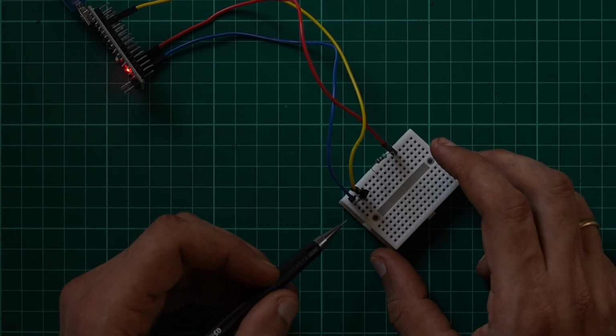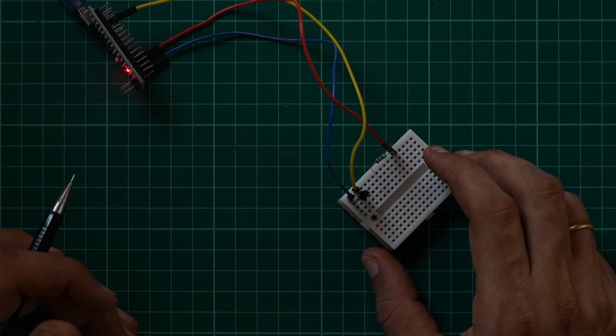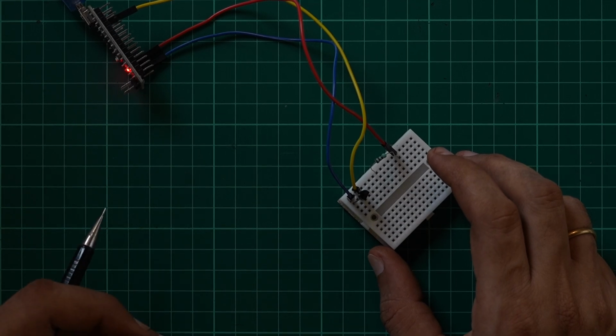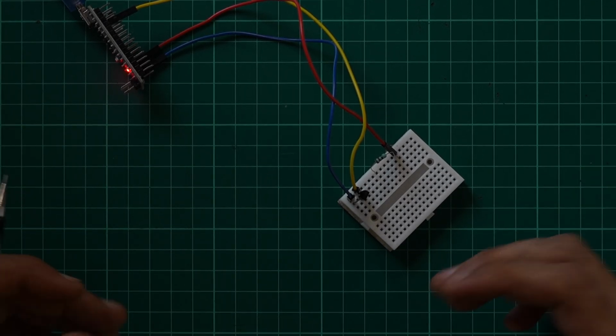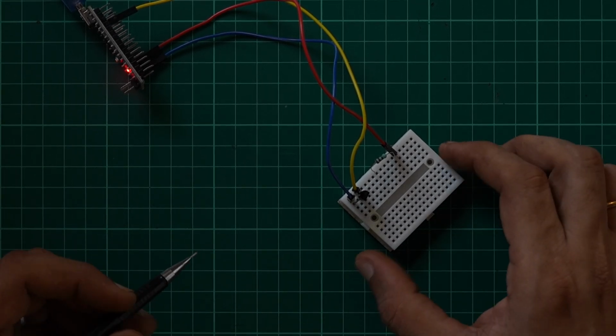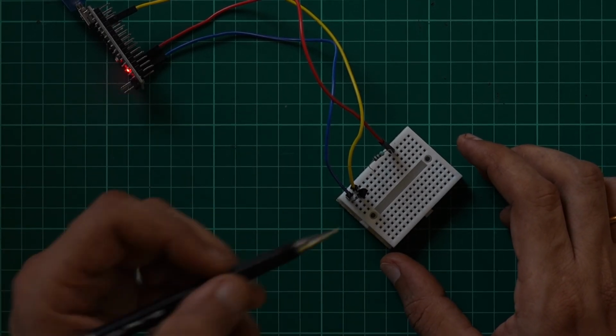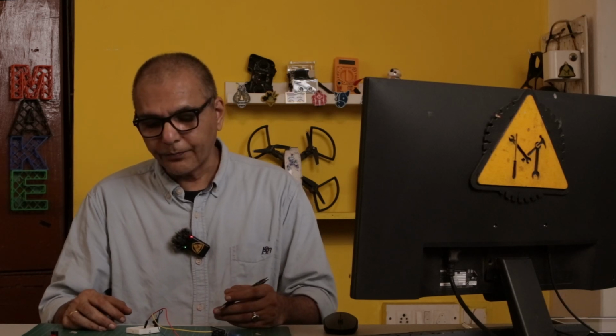Now, one thing to remember is that the Arduino GPIO, or the digital I/O pins, have a limitation to the amount of current that they can supply to a load. You can't connect a big relay or a big motor directly to this device, because it cannot provide that much current. So how do you operate those devices? That's where your transistor comes in. The transistor just requires a very small signal on its base, which is our yellow wire or the GPIO pin. And then depending on what type of transistor you use, you can use even large ones connected to a big heat sink that can draw a lot of power, and they can power really high power devices like motors or heaters or relays.